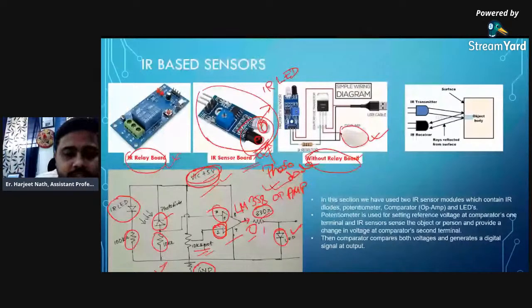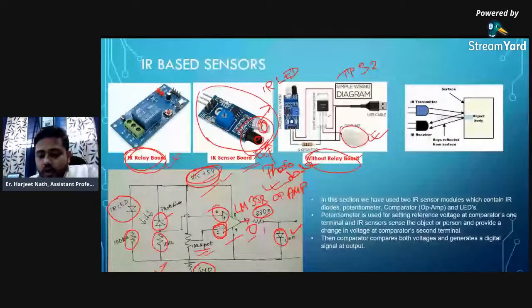Now in order to connect this motor, you need to have two different setups. One setup is either you can go with a relay board, or you can use another kind of PNP based transistor, which is the TIP32C transistor. So you can either use a relay or a TIP32 PNP power transistor. So both could be used.